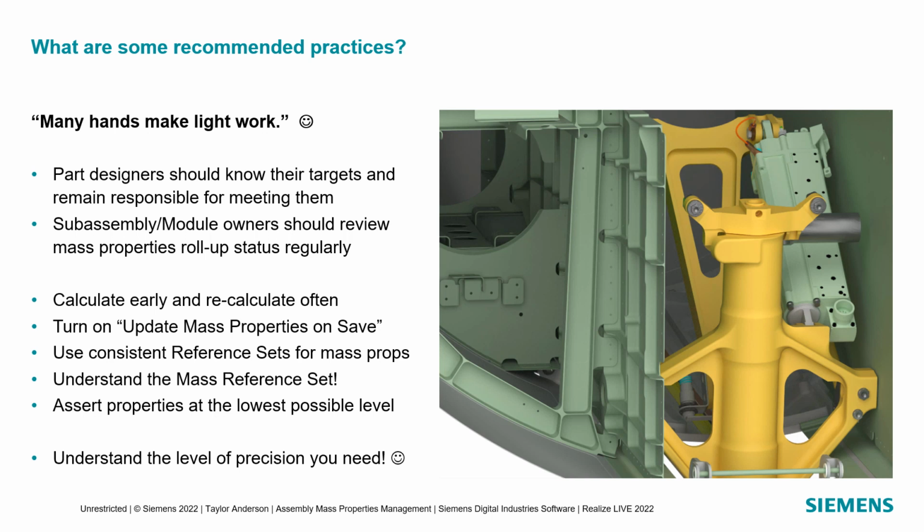If you're updating associative expressions for the parts, they're going to need to load more of the part than the minimal load. And that's going to require a little heavier load, right? Sometimes a lot heavier load if you've got very, very large assemblies. So that's one to keep an eye on. Again, if you've got very large assemblies, you may avoid setting that customer default for associative expressions.